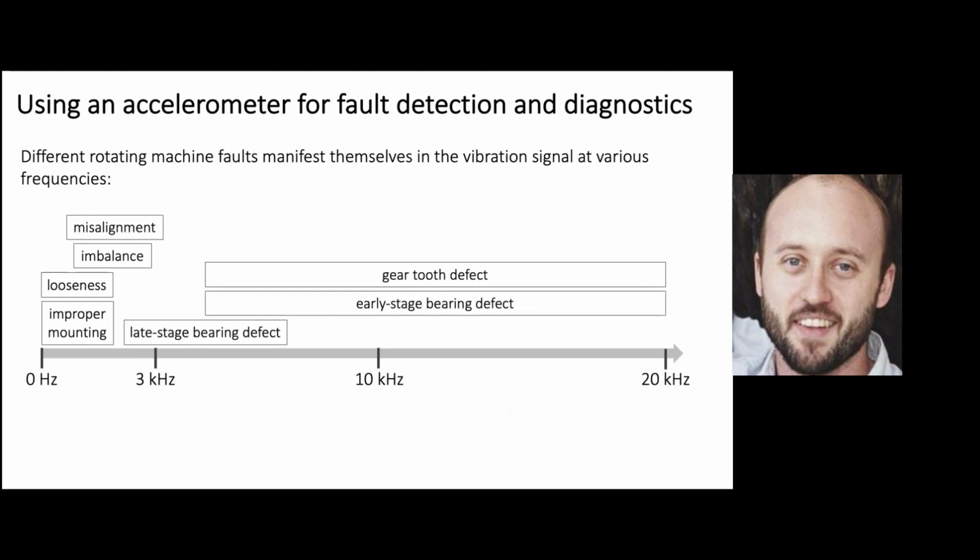So now this, in the light of our discussion on system frequency response and accelerometer frequency response, we can start to understand how these characteristics of bandwidth and sampling frequency are important for detecting various defects. So remember, the bandwidth is that flat period of one-to-one transmissibility.